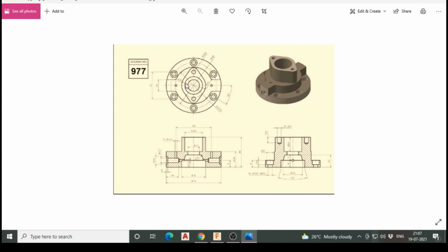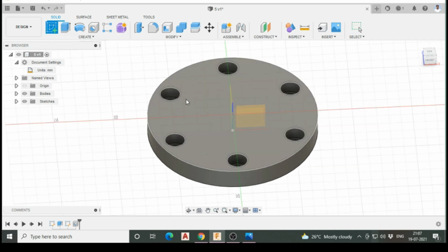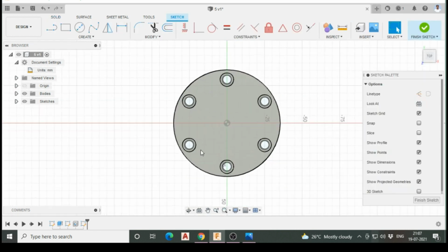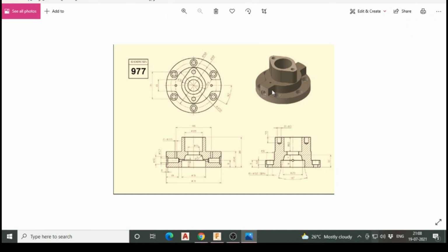The next thing we have to create is this shape that has been extruded from the surface of the base. So we have to create this sketch now. What we'll do, we'll come over to our design again, we'll activate our sketch tool, we'll select the face on which we want to create our sketch. You can see the face has been activated, and we have to make sure in which direction we are creating. Here you can see we have to create somehow like this horizontally, right?